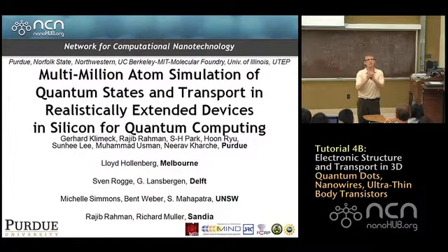So every atom has a certain strain energy associated with the distance of its neighbors. So it basically looks at 4 neighbors and figures out, okay, you're that far away, you're that far away, you're at that kind of angle. Therefore, I accumulate a certain amount of strain energy. And you do that for everybody, and you don't double count. And then you let them sort of loose in the numerical sense, and they sort of figure out where they would like to sit and minimize the total energy of the system. Does that make sense?